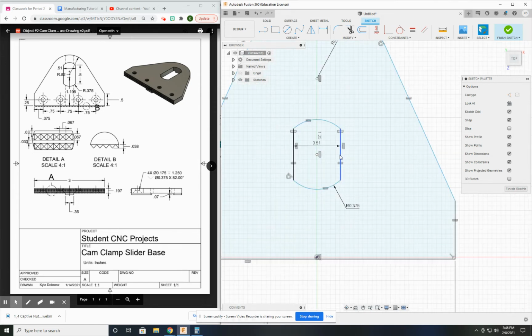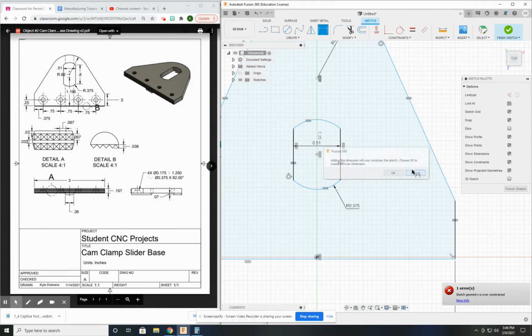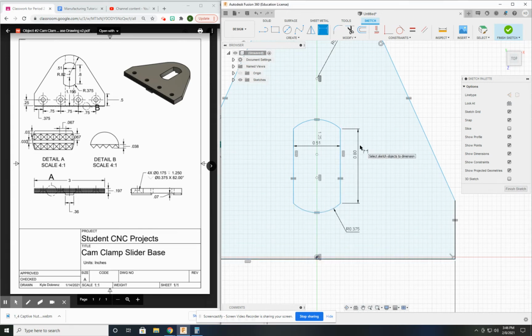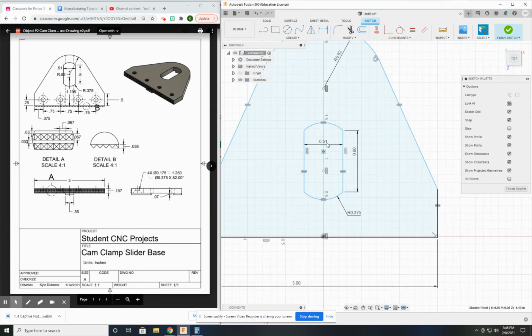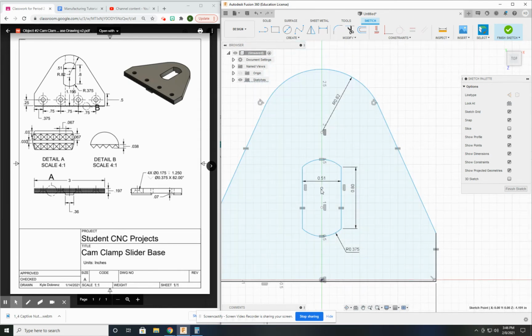Didn't like that either. Okay, let's delete the horizontals. Try that again. Sometimes the computer gets a little goofy, so we got to play games from time to time. Let's try this. So if I do endpoint to endpoint, no, it does not like that. Oh, look at here. It put in a tangent. That's what's going on. That's why we don't want tangents sometimes. They keep us from doing what we want to do. Should have caught that earlier, but no big deal.